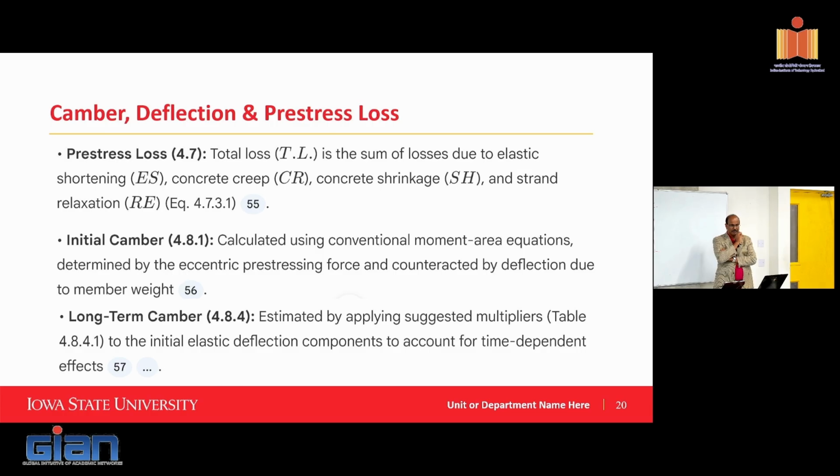I earlier mentioned that prestress takes advantage of the high strength material properties, including concrete and prestressing steel. If you don't have that high strength, the losses basically will wipe it out. And that was the reason why prestressing wasn't successful when initially people tried it. There are cases where people first thought of this idea, they tried to prestress it with reinforcing bar. 3 months later, the losses basically wiped out the prestress and the structure became ineffective. So this high strength is a huge benefit in terms of using it for prestress, but the losses have to be accounted for.